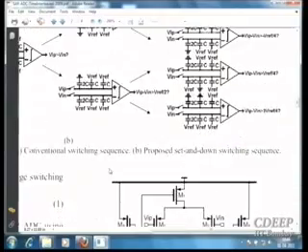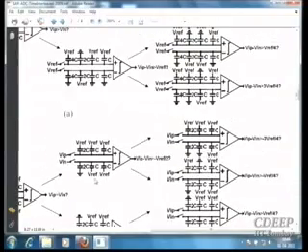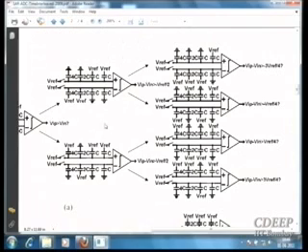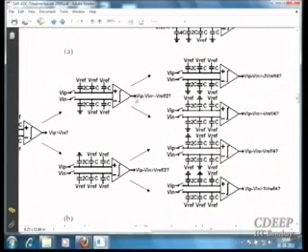They have also done an analysis of energy dissipation. It is obvious, right? Because you have less switching to VREF. Look here, for example. This capacitor 2C was grounded. Now, if you go to down conversion, you will get VREF, or actually up conversion, meaning it will be greater than minus VREF by 2. It will be connected to VREF, so you will draw power from VREF. But now you will have less switching here, because one side will remain constant.